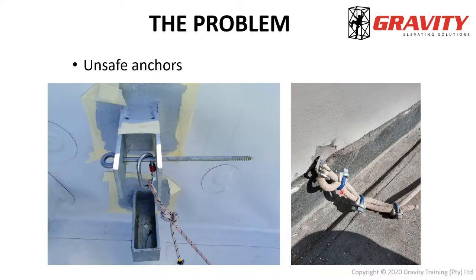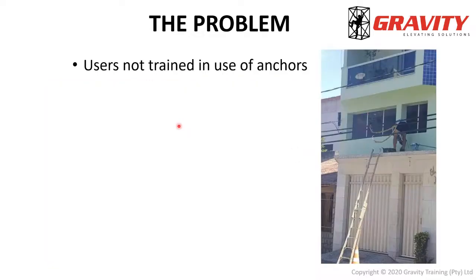The mechanical connection of those saddle clamps is designed to work with steel cable or steel wire rope. So the effectiveness on a kernmantle rope is untested, unproven. And this anchor point, not tested, not marked, is also a danger, which leads me to believe that if this system should experience a shock load or a fall impact, it will not hold, it will not be sufficient to protect the user sufficiently.